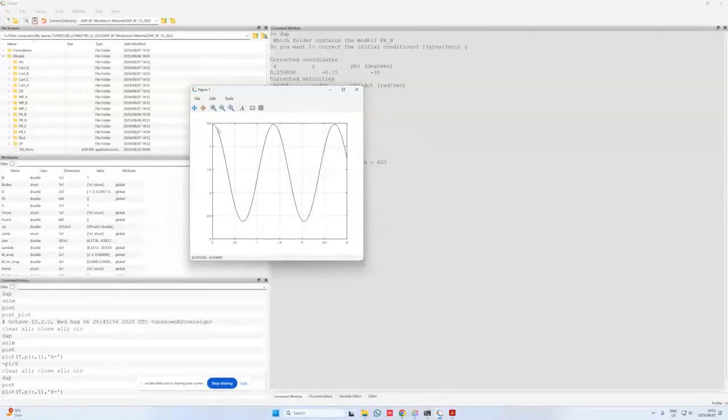Okay, so I do see the oscillatory effects of the gravity on the pendulum rod. I don't really expect a decrease in the amplitudes because I don't have any resistive forces acting on the system. So these constant oscillations, constant frequency and periods give me more confidence in the results that I now got over the time range that I specified.